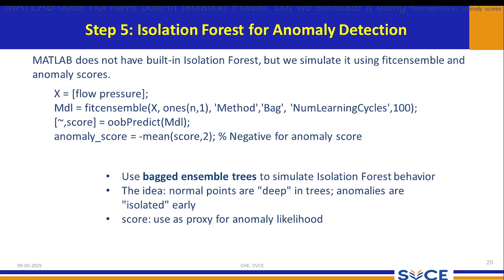And coming to step 5, isolation forest for anomaly detection. So we are going for unsupervised learning. MATLAB does not have a built-in isolation forest, but we simulate it using a code called fitensemble and anomaly scores. Let's say X is equal to flow and pressure, Mdl equals fitensemble of X, ones of n comma 1, method Bag, number of learning cycles 100.